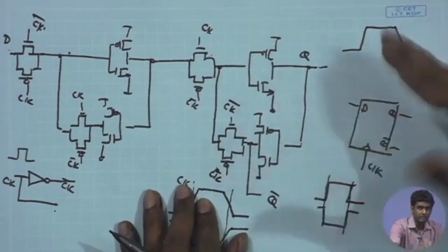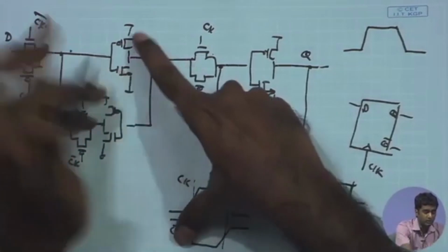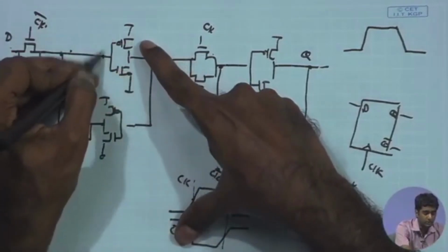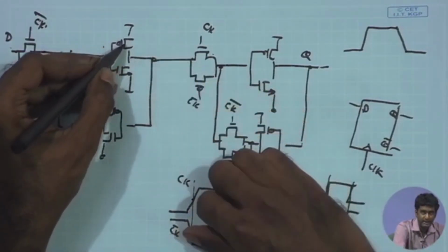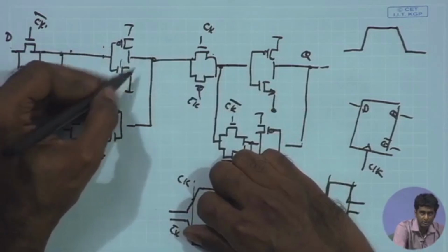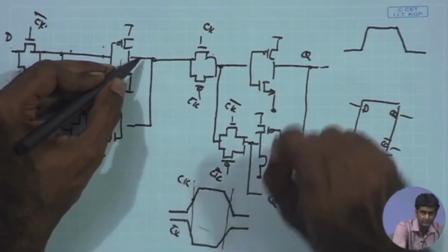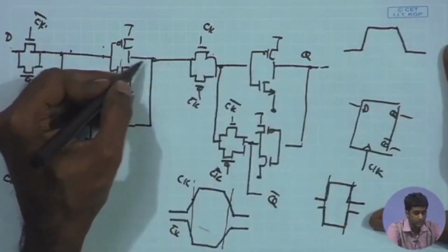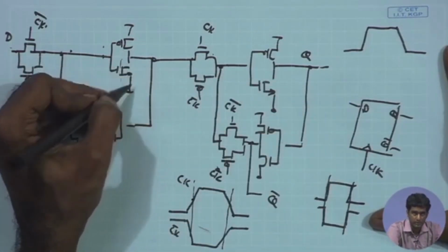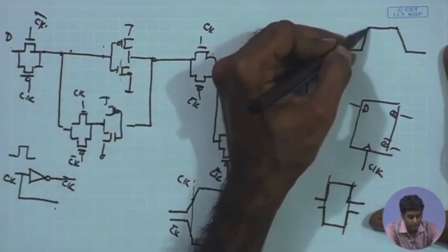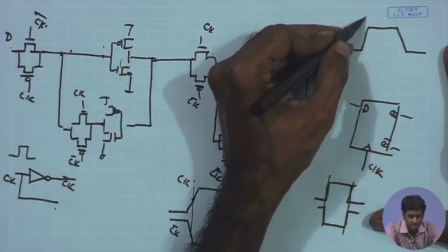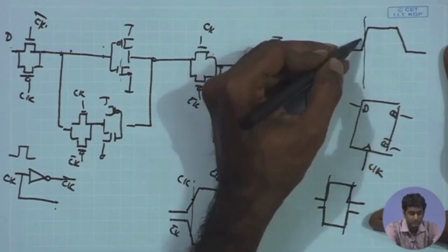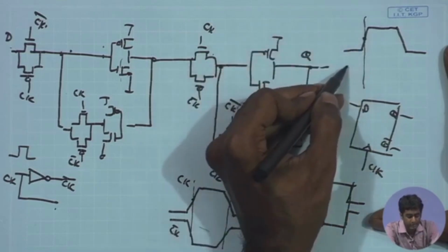So, the inverter will have some finite delay, because as we know when the input over here goes up, it will take some finite time for the NMOS to discharge it. So, it will be discharged completely after some finite duration. So, approximately once again it will be leading to a downgoing voltage over here, gradually only it will be discharged. So, it will have a slope, and with respect to the midpoint of transition of the input, it will have some additional delay.